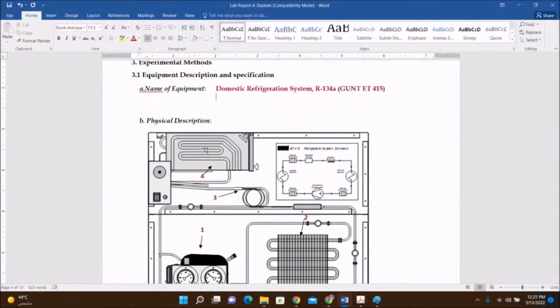Its boiling point and melting point are very low, even negative. So at room temperature, or the water temperature, heat will be absorbed from the water by the refrigerant, or the refrigerant will absorb heat from the room, space, food or water, and it starts boiling. It evaporates and forms a vapor. So the outlet of the evaporator is completely vapor.